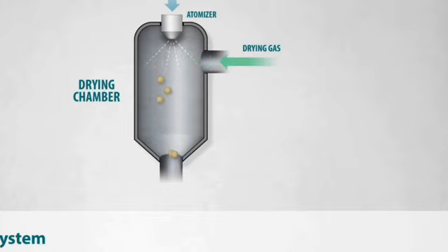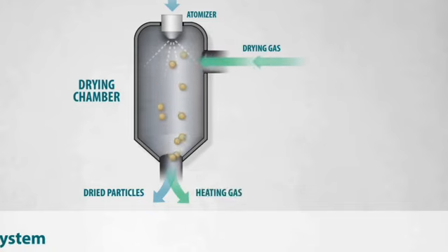Then, the feed may be concentrated by removing some water to reduce the energy required for drying. It can also be preheated slightly to lower its viscosity and bring it closer to its evaporation point. Proper feed preparation ensures the final powder is uniform, free-flowing, and high quality.